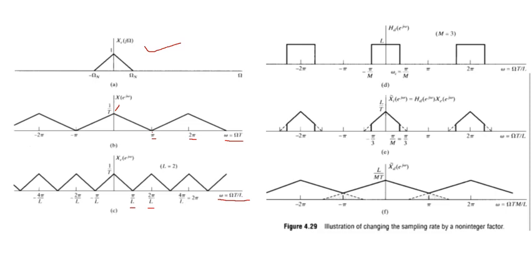Now we will pass it through the filter. Because pi by 3 was minimum compared to pi by 2, we have used the cutoff frequency to be pi by M, minus pi by M, then its copies. So this is the decimation filter that we are using here. Once we pass this Xe, the expanded signal, through this, obviously this pi by L, the value of L is 2, so this is pi by 2, this is minus pi by 2. If we pass this through the cutoff of pi by 3, this will cut off at pi by 3, so we will get this interpolated signal.